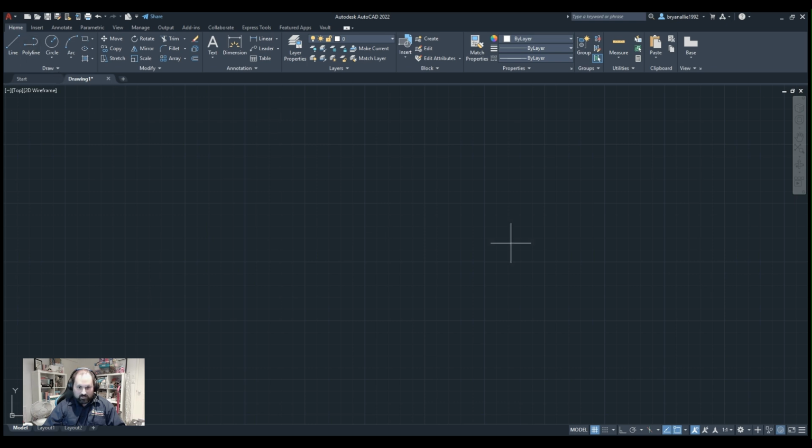So I'll do polyline, and if I press F8, that also turns on ortho mode. I'll do the first dimension, which is the base, which is 115 at 0 degrees. Then just select it again. Then I'll do the side, which is 20, and I can also do the other side, which is 20.